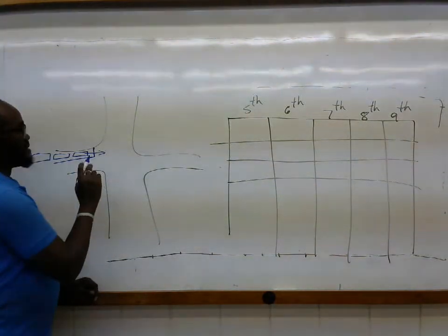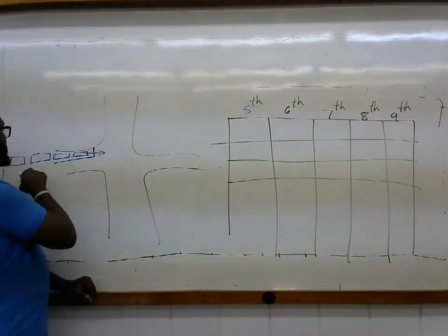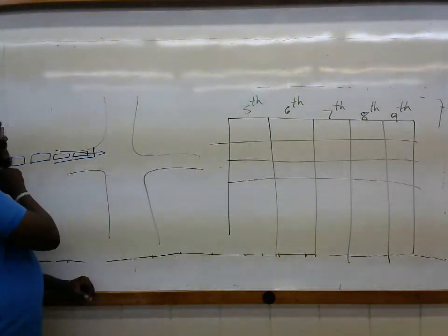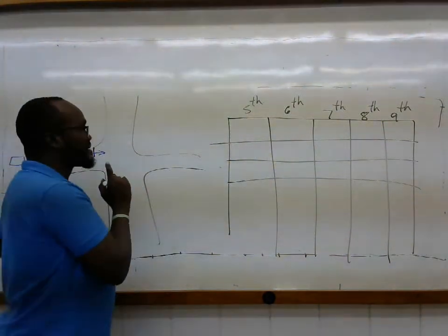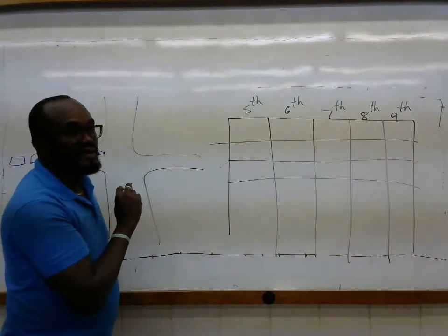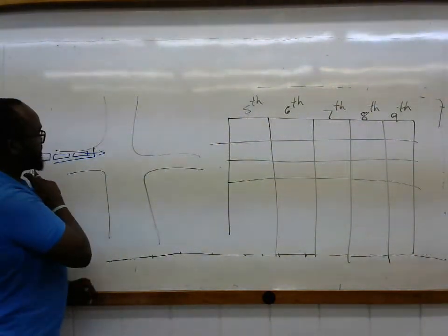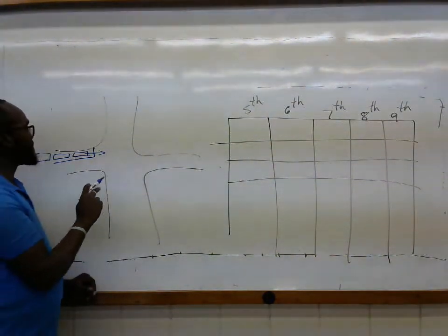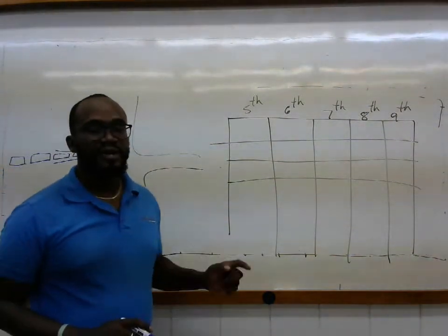So the theory is that once the fourth vehicle passes, it is assumed that the fifth vehicle would have gotten up to, if not cruising speed, something closely resembling cruising speed, from which you can then assume that the traffic stream is moving uniformly through the intersection, and then you can start making your saturation flow rate computations.